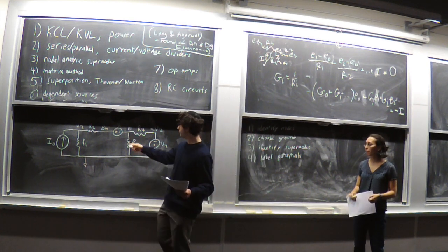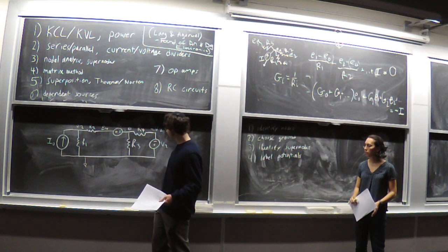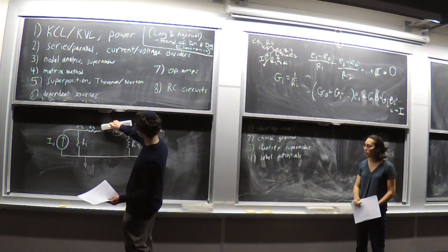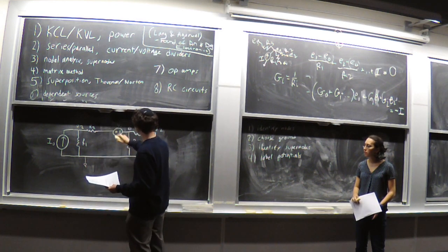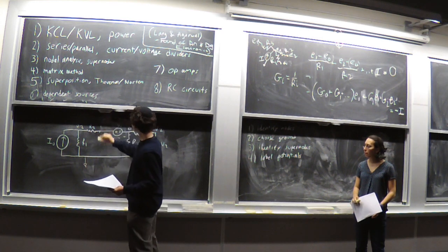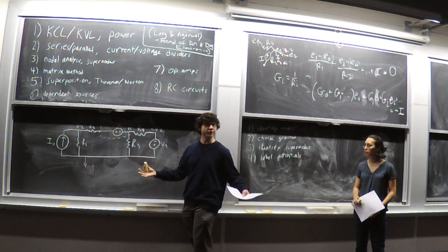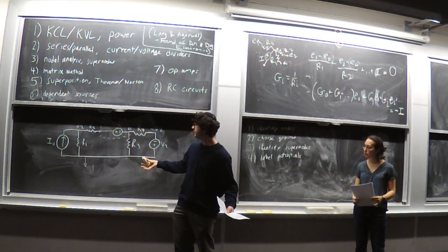And then, we see that we have this supernode here. So the way we deal with this supernode is that we want to view it as one, so I'm going to get rid of E4 and leave E1. And then what we do is we view this really as a single node. It's just a bigger node because it has this voltage source stuffed inside it.